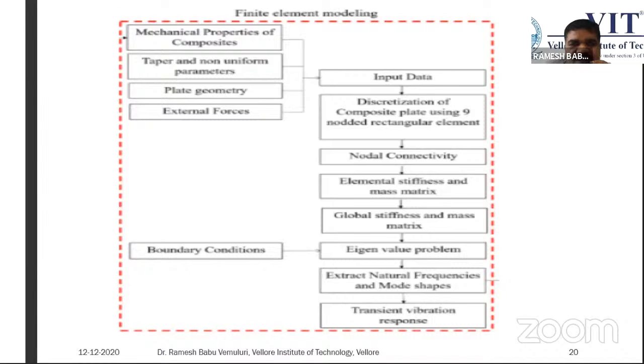And once you consider this, how each element is connected to another element is called the nodal connectivity. While connecting, there should be continuity. So there is C0 continuity, C1 continuity, and C2 continuity, whatever. These continuities are based on the order we have. Let's say we have the first order, then we go for C0 continuity. The second order gives C1 continuity, and the third order equations give C2 continuity. So this way, the nodal connectivity of elements works. I'm just revising those things.